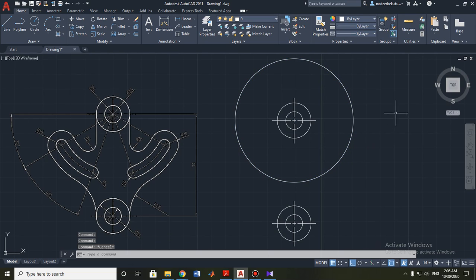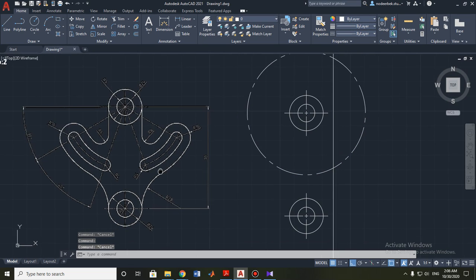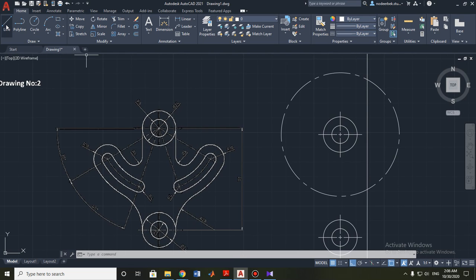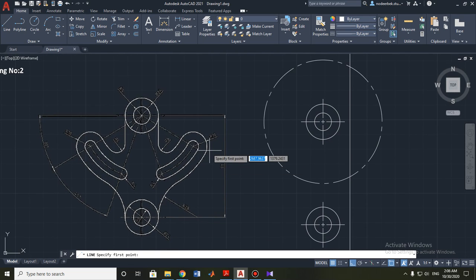And then I will change the type of line, the style of line, to center. Then it's time to build this part of our detail. What I will do is, using the line tool again, I will start building a line. I will turn off the mode Alt. I need to go down, and then here I think the angle of this line will be 30 degrees. Yeah, the length of this line will be 42 millimeters.